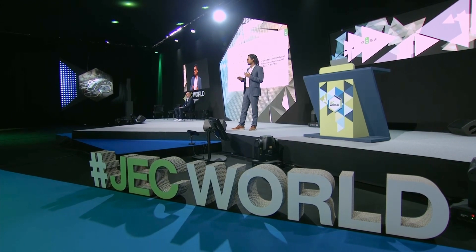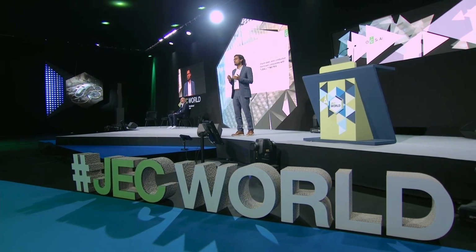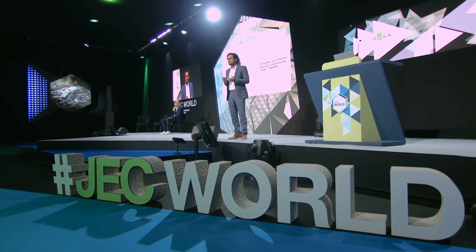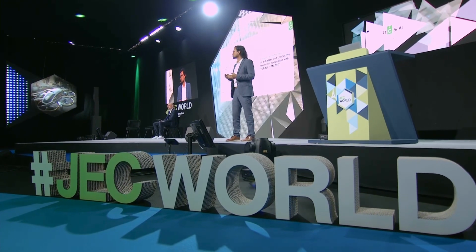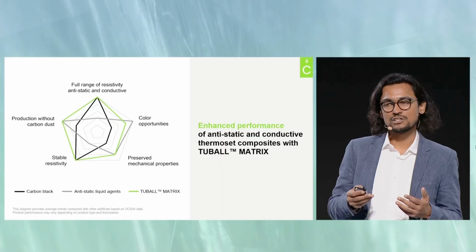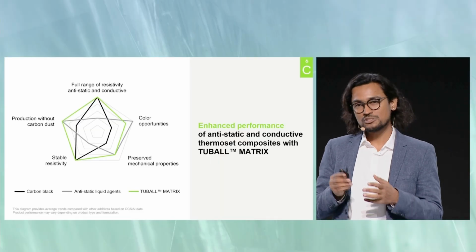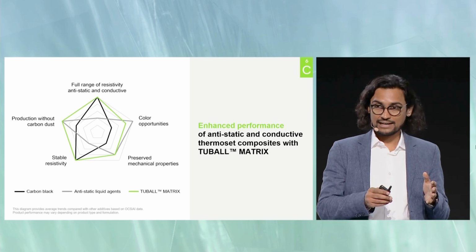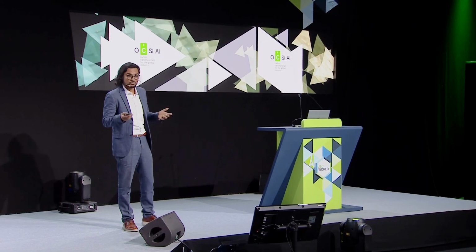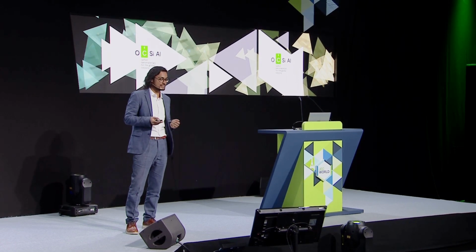Comparing it with some other conventional fillers like carbon black or additives like ammonium salts, which also give conductivity, nanotubes give a unique advantage of the possibility of giving a color, at the same time maintaining a very clean production facility, which is not possible if you are using carbon. Everything becomes black. I'm not very sure who's the fan of it.